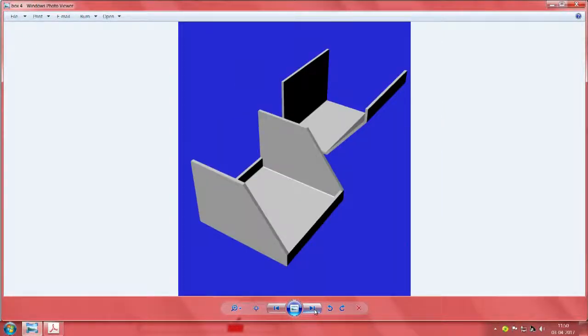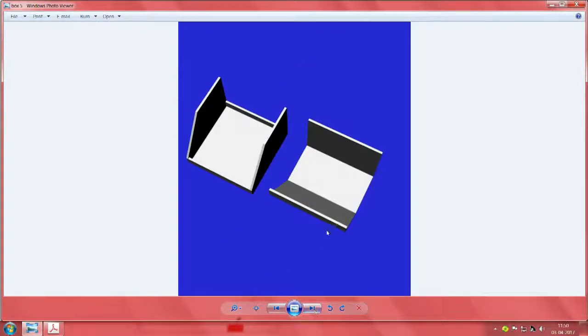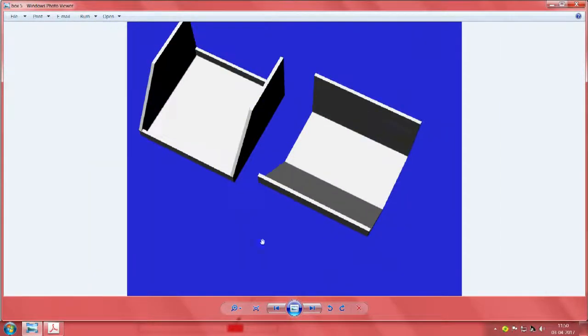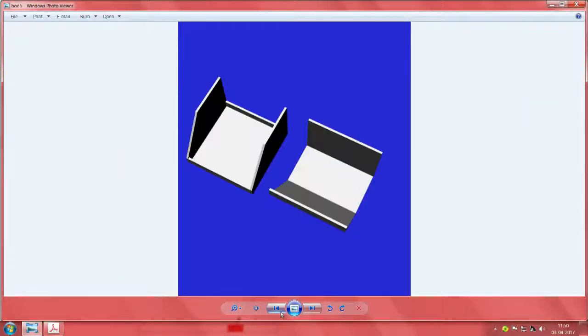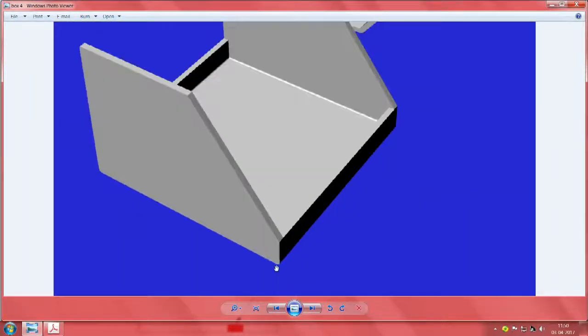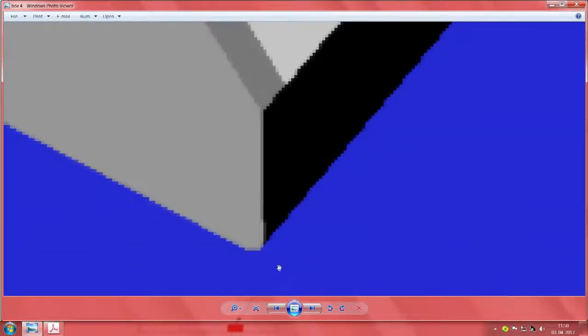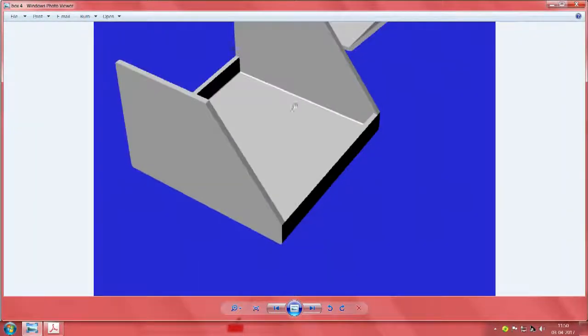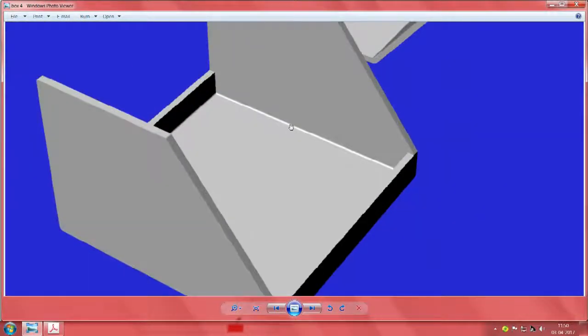Now, already I have made a small jump here. Have you noticed? While this one is a sheet metal enclosure with only a thickness, in real life when you want to carry out the bending, as we have seen in the demonstration downstairs, there is a radius that involves 2 radiuses. One is an internal radius of the tool when we try to do the bending on the bending press or the brake, and then the sheet thickness itself.